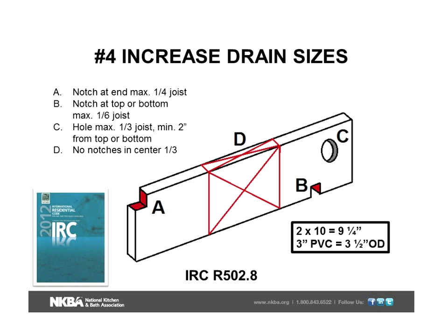But let's say you do have floor joists. Let's say your floor joist is a 2x10. Well, a 2x10 is actually 9 1/4. And the code says that the hole can be no more than 1/3 the size of the joist. Therefore, the PVC outside diameter, 3.5, would be more than 1/3 of the height of that joist.